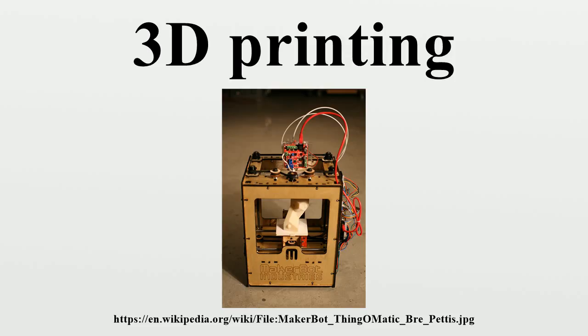Electron beam melting is a similar type of additive manufacturing technology for metal parts. EBM manufactures parts by melting metal powder layer by layer with an electron beam in a high vacuum. Unlike metal sintering techniques that operate below melting point, EBM parts are void-free.